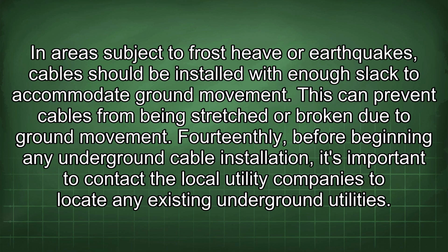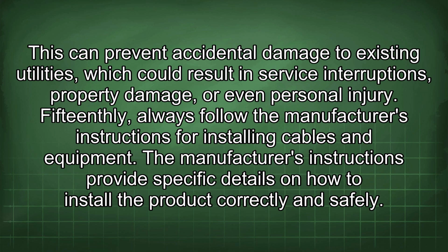Fourteenth, before beginning any underground cable installation, it's important to contact the local utility companies to locate any existing underground utilities. This can prevent accidental damage to existing utilities, which could result in service interruptions, property damage, or even personal injury. Fifteenth, always follow the manufacturer's instructions for installing cables and equipment.